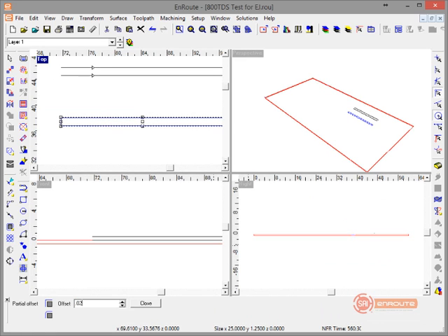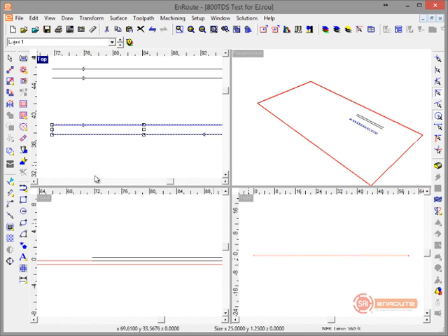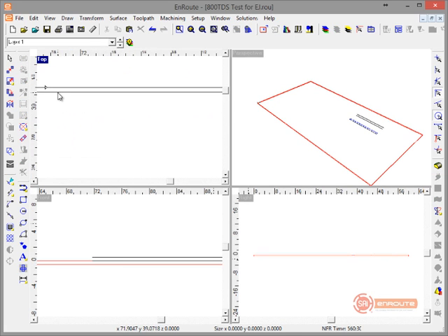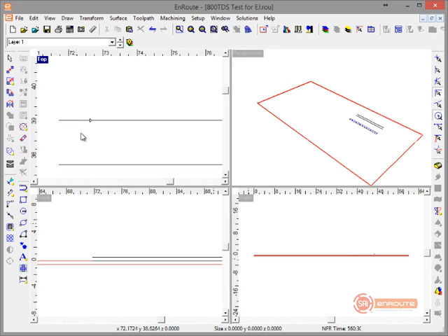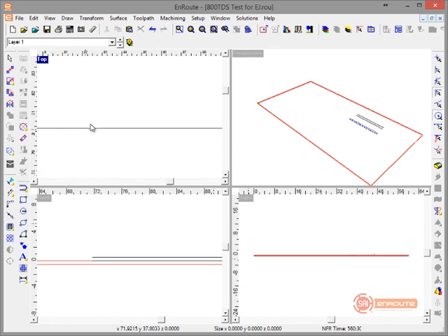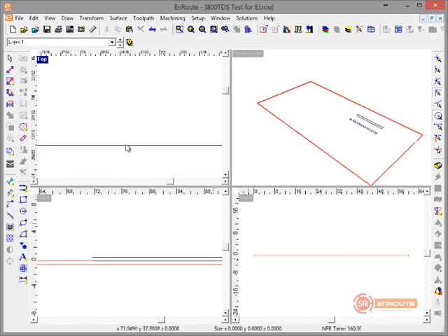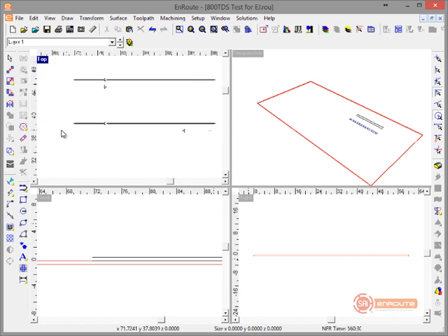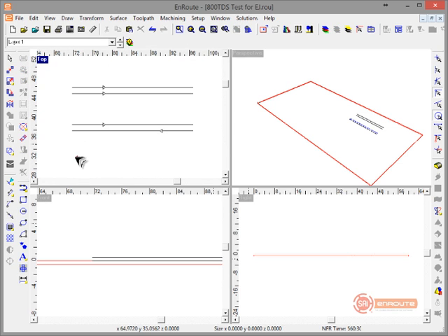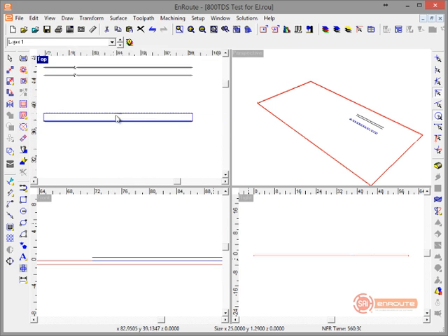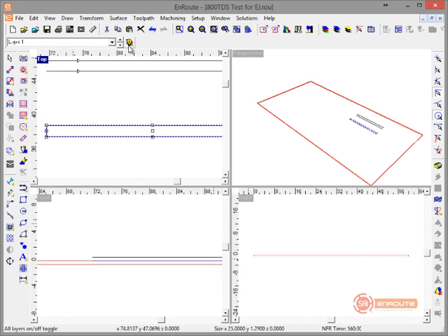Let's say 0.02. I'm going to click here and go to this side, click here and then go to this side. Make sure I did that one. All right, now that should give me these contours. Make sure I don't have more than one. I do. All right, and now just by connecting these, the sides will be the same, but I'll be going past the edges of the top and bottom a little bit because of those offset values.